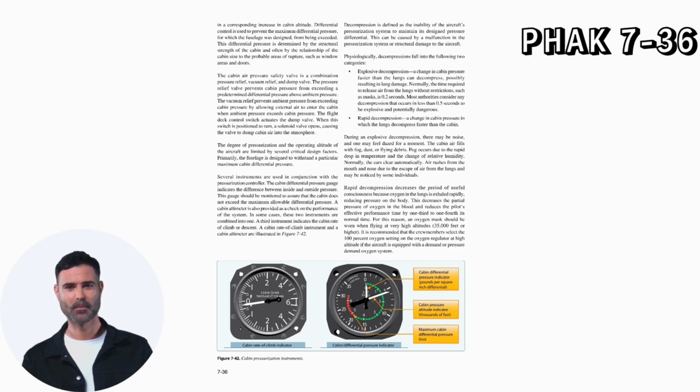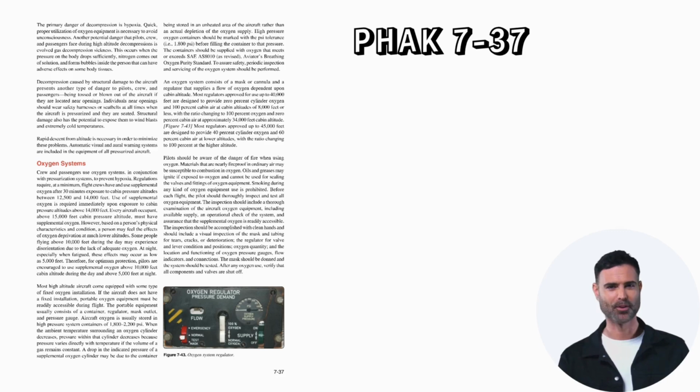This can be caused by a malfunction in the pressurization system or structural damage to the aircraft. The primary danger of decompression is hypoxia. Quick, proper utilization of oxygen equipment is necessary to avoid unconsciousness. Another potential danger that pilots, crew, and passengers face during high-altitude decompressions is evolved gas decompression sickness. This occurs when the pressure on the body drops sufficiently, nitrogen comes out of solution, and forms bubbles inside the person that can have adverse effects on some body tissues.